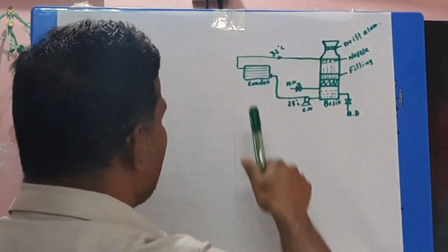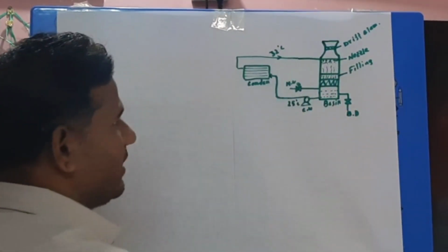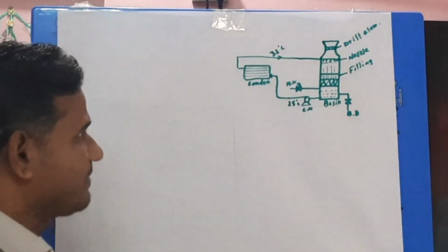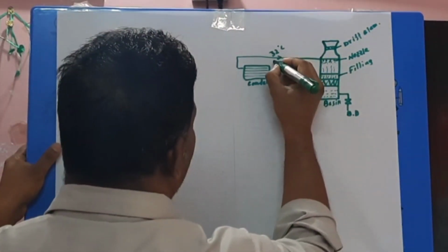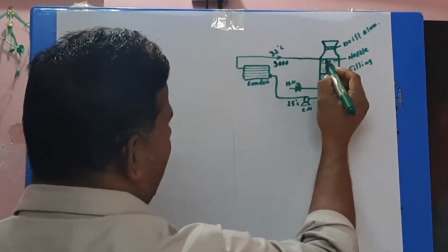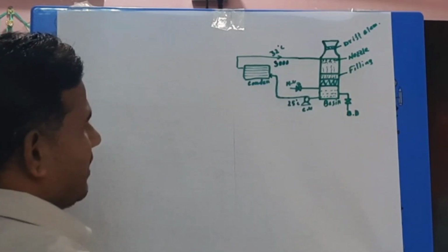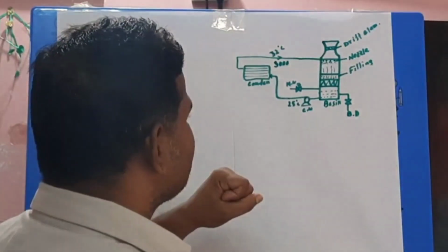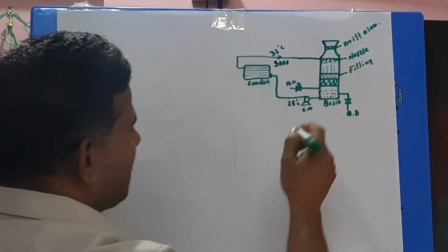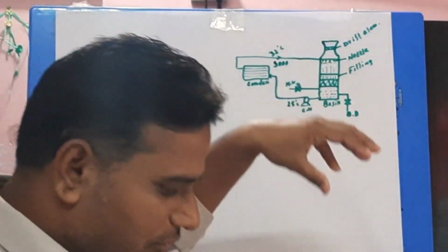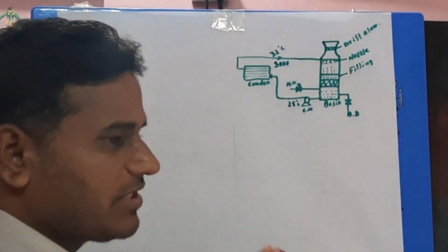So for reducing this high temperature, we are providing this cooling tower. In this cooling tower, we are reducing the temperature. How are we reducing this? Now I will explain. You think this 3000 flow is coming to the header. This is the cooling water header. After coming to the header, this set of nozzles is available. So when this water flow passes by this nozzle, the water surface will be increased. After increasing the water surface, it will come down on the filling. If it passes by the filling, the velocity will decrease.